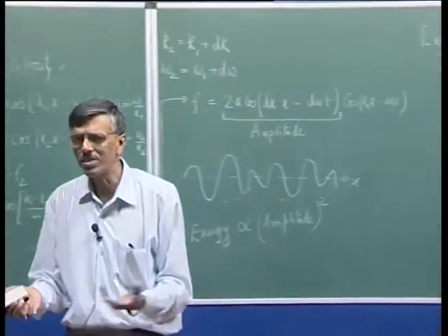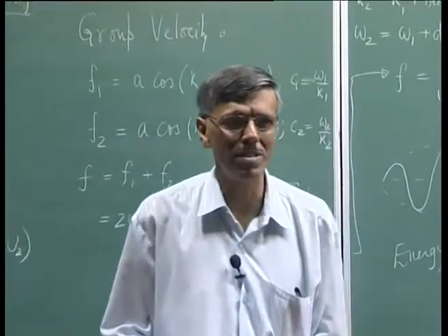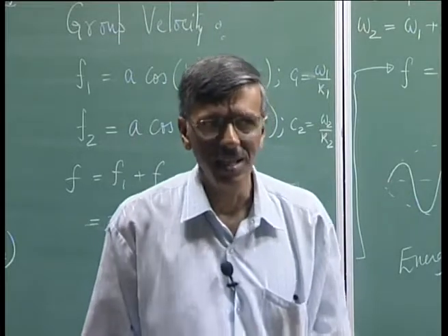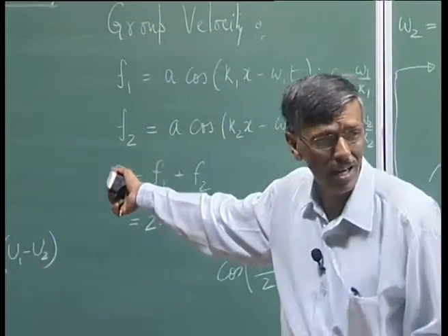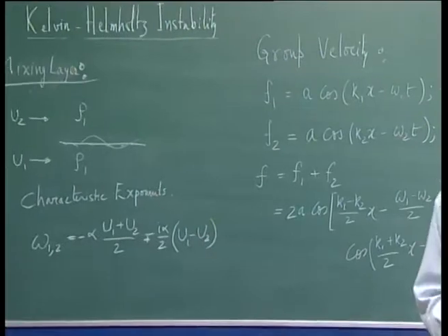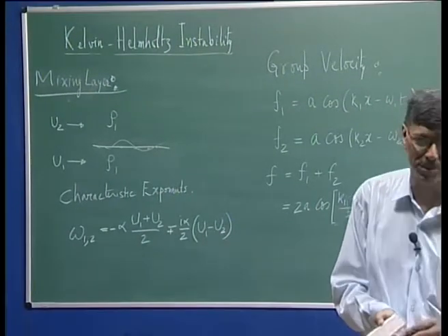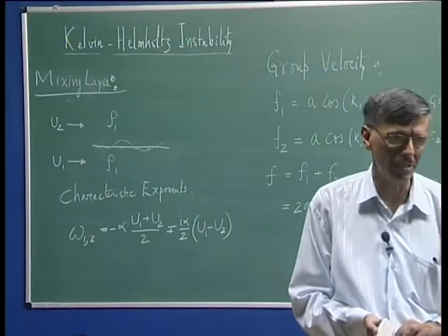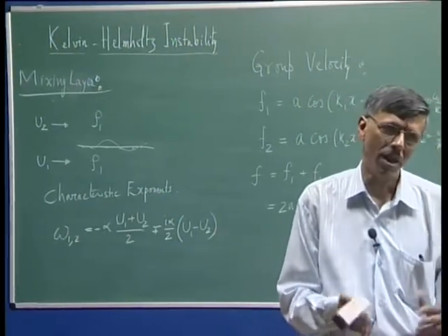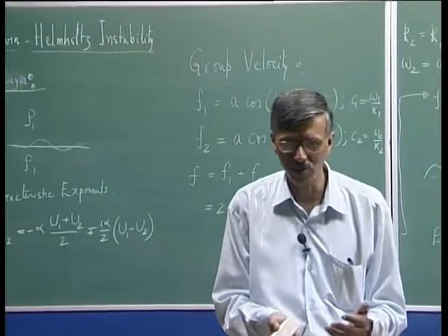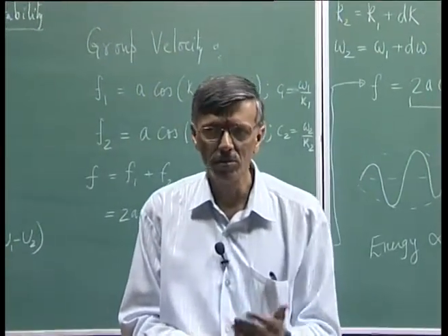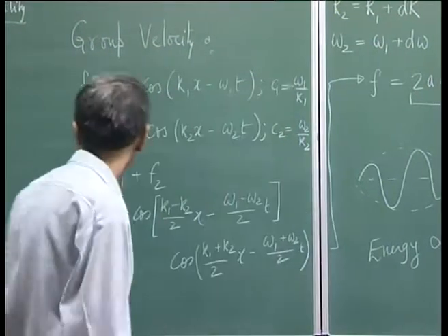Okay. So, this k that we talked about is basically the wave number vector. It could go in any direction. What we were studying in the context of Kelvin-Helmholtz instability, that k had two components. The x component was alpha, the y component was beta. So, I would also have a group velocity as a vector. And the individual components will be given by the corresponding relation.